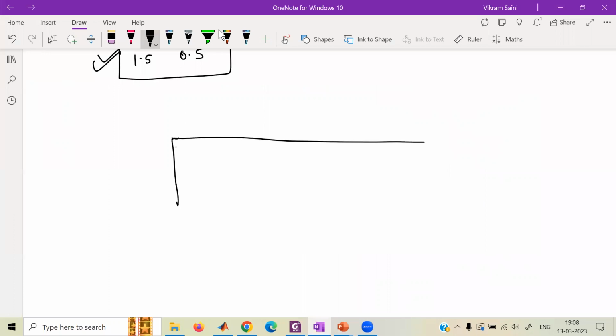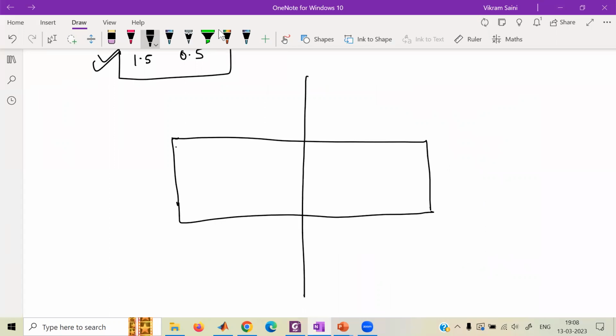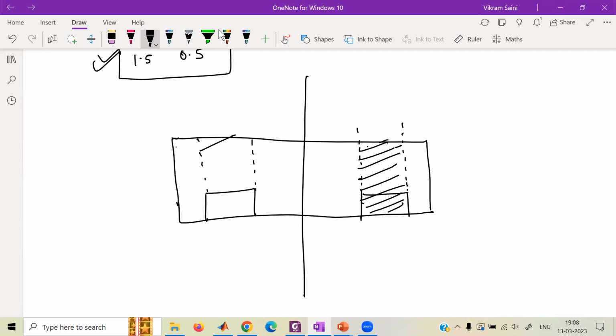So let's say this is the wing. This is our center line. One aileron, the other aileron. What is happening here? When you deflect this aileron, the camber on this part of the wing changes. I'm assuming everybody understands what camber is. The camber changes on this part also because both of the ailerons are deflected. One goes up, one goes down.